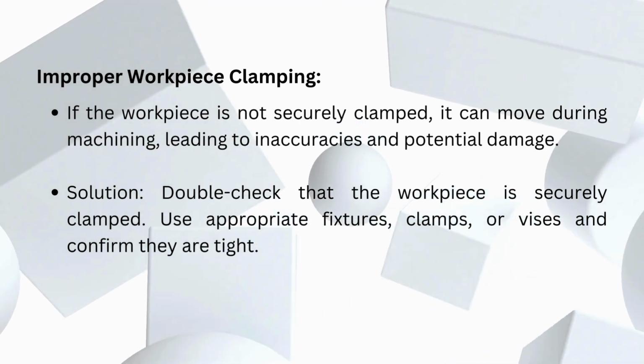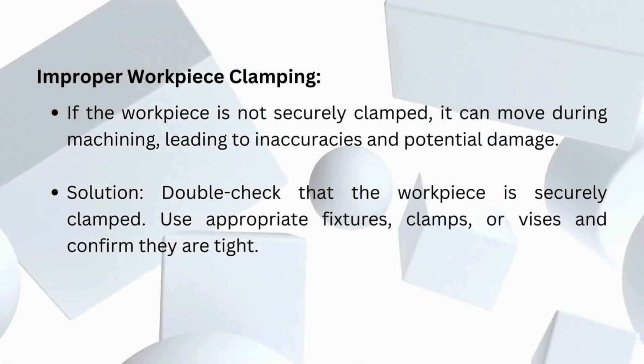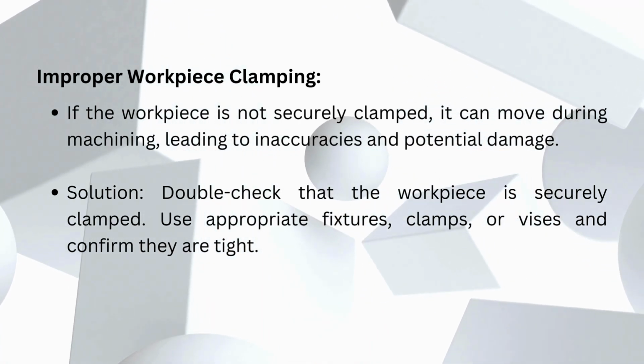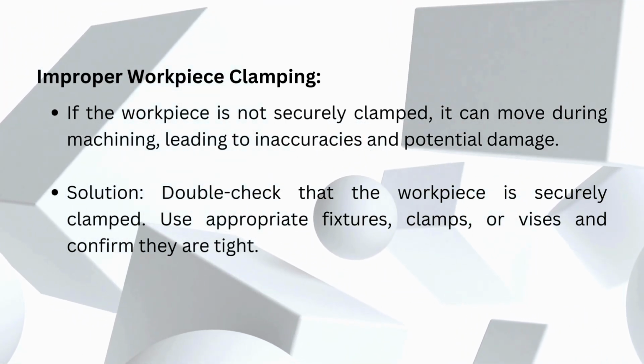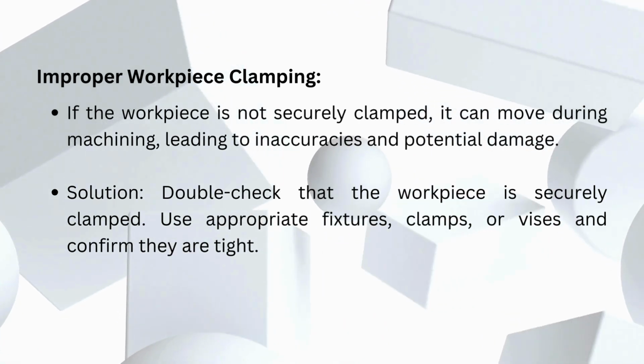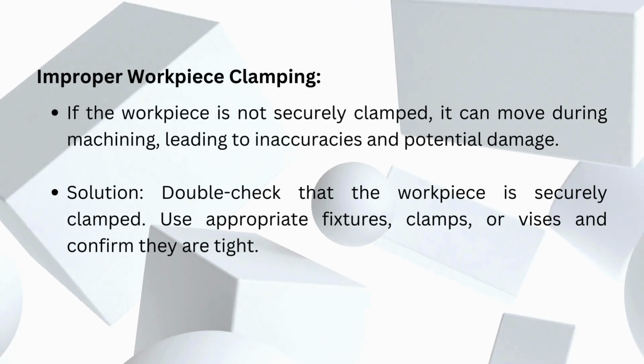Improper workpiece clamping. If the workpiece is not securely clamped, it can move during machining, leading to inaccuracies and potential damage. Solution: double-check that the workpiece is securely clamped. Use appropriate fixtures, clamps, or vices and confirm they are tight.